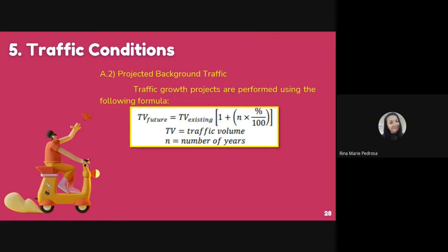If there are not sufficient traffic count data to determine the traffic growth rate, or historical traffic indicates negative or low growth, for the purpose of the TIA, an average annual non-compounded growth rate of 2% should be used as a lower limit for provincial highways.